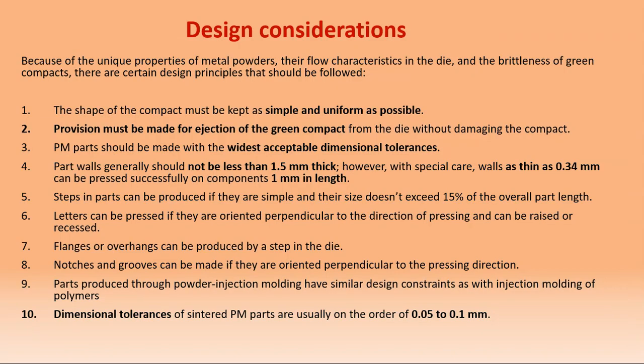Okay, for design considerations, when you want to design parts for powder metallurgy or injection metal molding, you have to keep the shape as simple and uniform as possible, and need to consider the ejection of the green compact without damaging it. It's quite fragile.